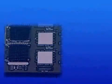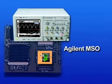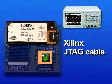The FPGA Dynamic Probe application is composed of three main elements: a Xilinx FPGA with a special Agilent debug core, an Agilent MSO running an FPGA Dynamic Probe software application, or a PC running an FPGA Dynamic Probe application connected via USB or LAN to the MSO, and a Xilinx cable that provides the physical communication via JTAG.